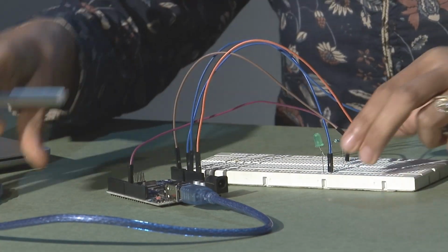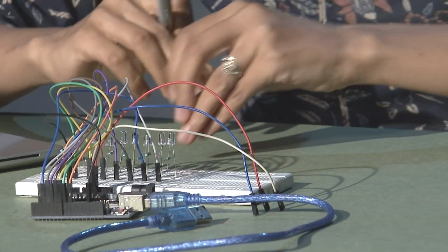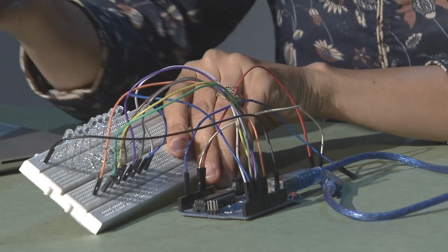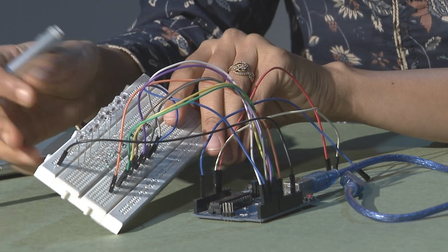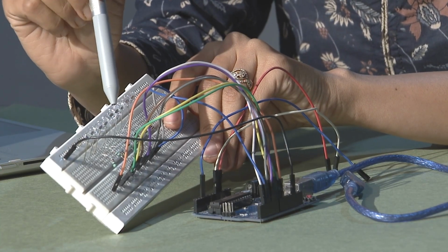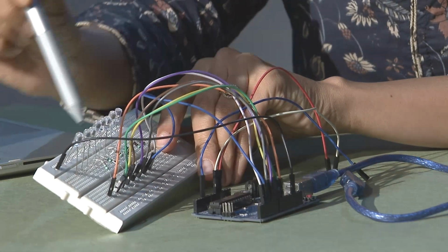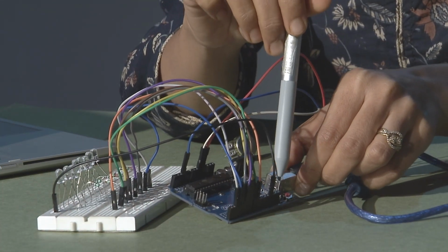And first of all, let me take out this connection and let us extend it further to a detailed one. So, I have one module ready for you here, and let me first explain the different connections that we have made over here. Here you can see a sequence of LEDs, and because this is the cathode terminal of the LEDs, I have used a common ground over here, and this particular ground terminal I have taken to the ground terminal of my Arduino board.